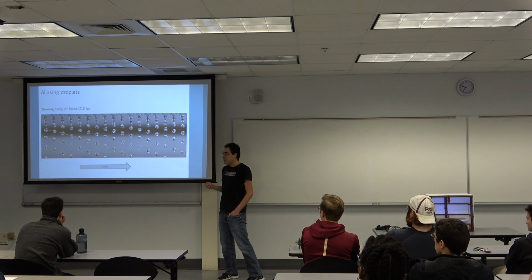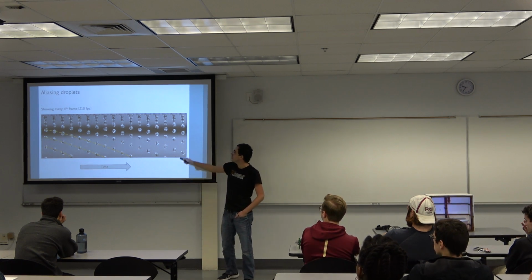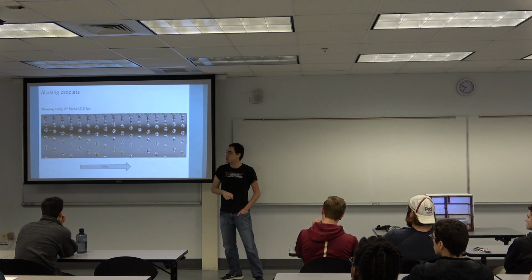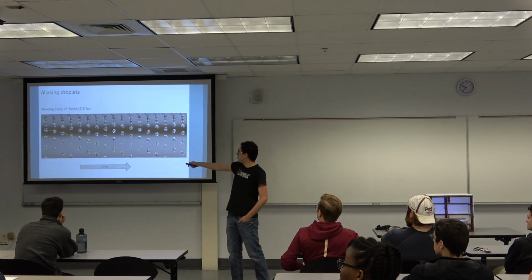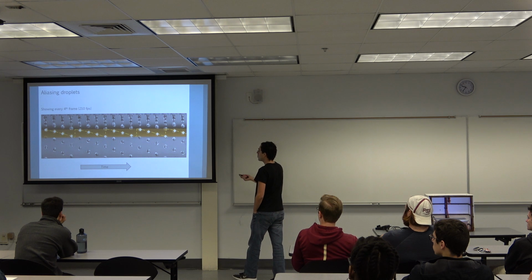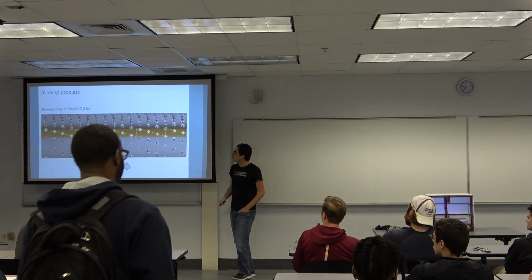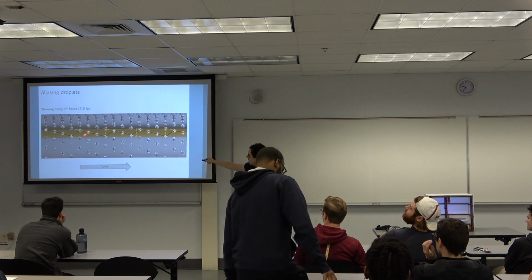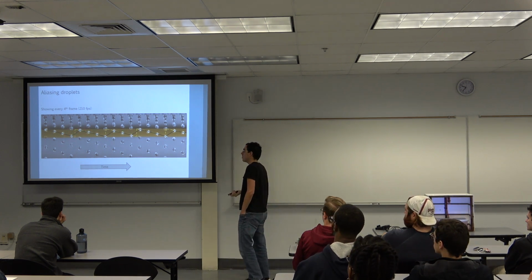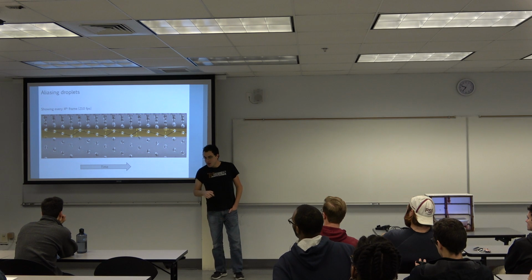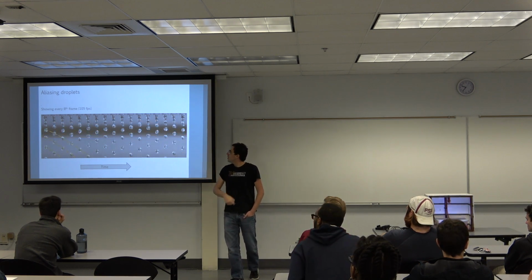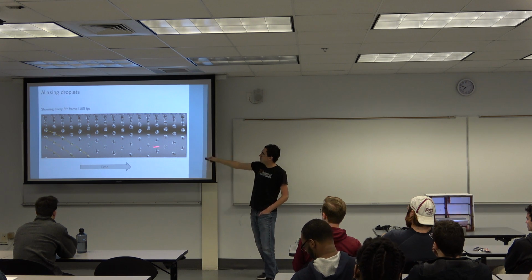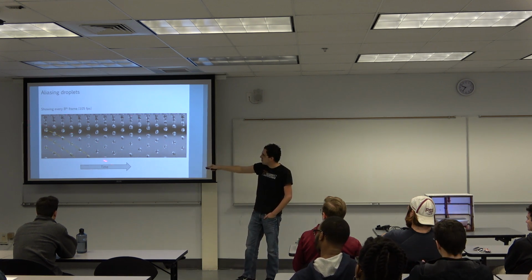If we decrease the sampling rate, so now I'm decreasing the sampling rate, halving it once again to 210 frames per second, then that's the true trajectory of the droplets. If now we focus at one, this is how it looks, and if we connect the dots, then the sawtooth wave looks a little bit more jagged because we have fewer samples to reconstruct. If we do it once again, so now I'm halving the sampling rate once more, and I'm showing every 8th frame, and you see the true trajectory.